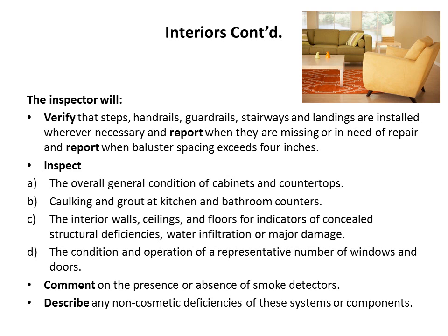Inspect the overall condition of cabinets and countertops, caulking and grout, and bathroom counters, the interior walls, ceilings, and floors for indicators of concealed structural deficiencies, water infiltration, or major damage, and inspect the condition and operation of a representative number of windows and doors. Comment on the presence or absence of smoke detectors, and describe any non-cosmetic deficiencies of these systems or components.